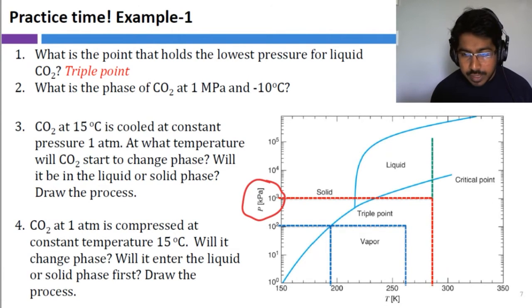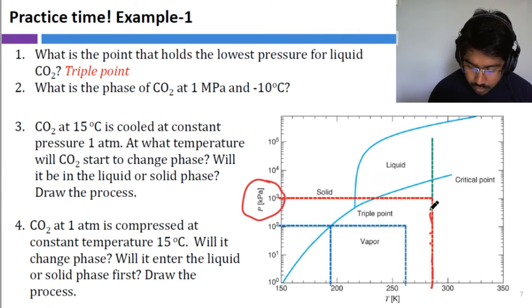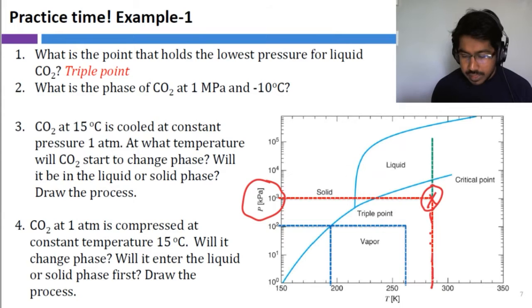it's given in Celsius, but in the figure it has Kelvin, right? In exam situations, if you panic too much and have not practiced too much, this could be an easy trap. You might look into this figure and say, okay, I don't have minus 10. How am I supposed to locate these points? But if you see this is Kelvin, then you will not be confused. Minus 10 Celsius is 263 kelvins. So basically the red line down here, we can go up there, and then we find this point, which is in the vapor region. Your friends got it perfectly right.